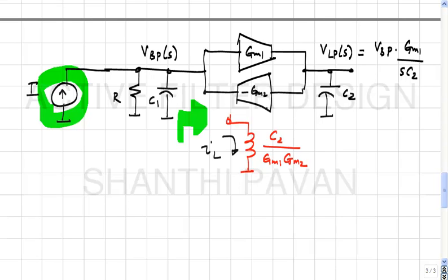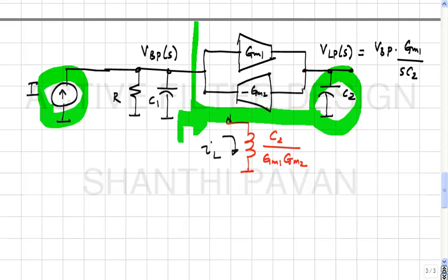And so therefore, what do you see? In other words, the voltage across this capacitor is basically proportional to the current that would have been flowing through the synthetic inductor. That makes sense because all that this two port is doing is taking this capacitor and making its voltage look like a current and its current look like a voltage.